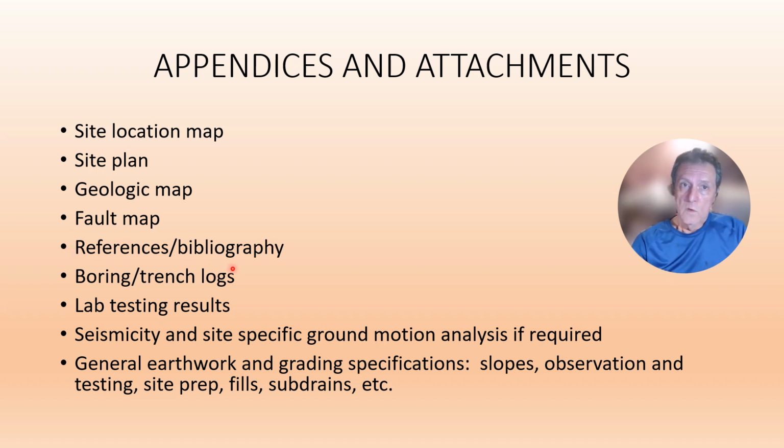The references you used, just like in college, you have to put together a bibliography and a list of references you used, which may include other engineering geology reports. You want to put in your trench logs and boring logs that show graphically and verbally what was encountered in those subsurface explorations, layer by layer.